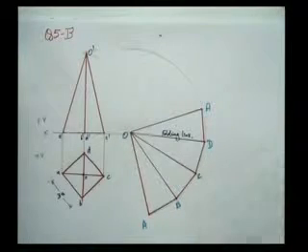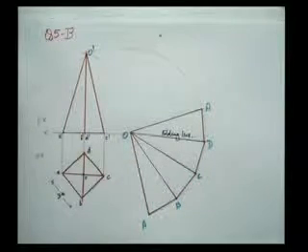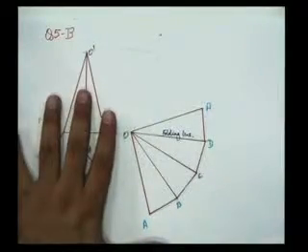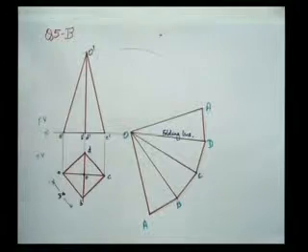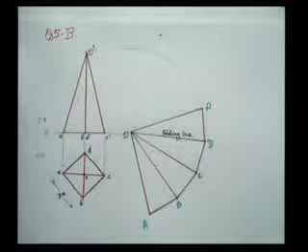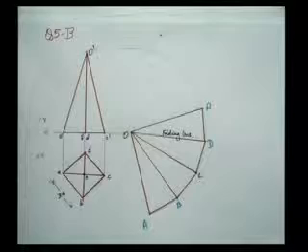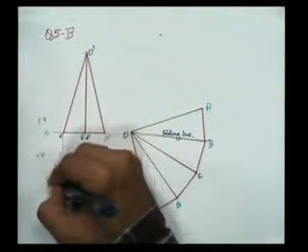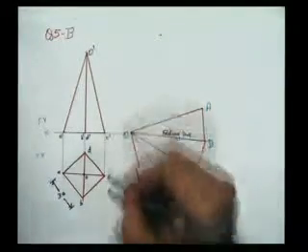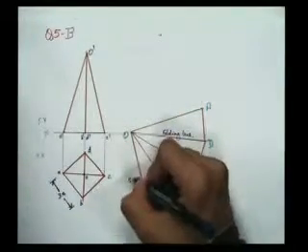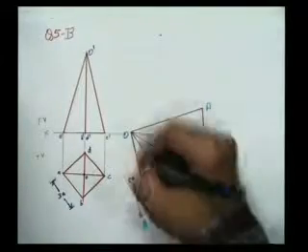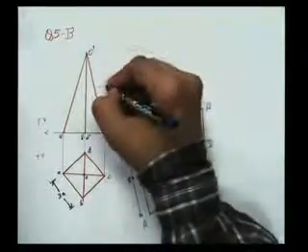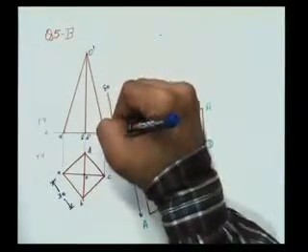That is why this is known as development of surfaces: this is a solid surface that is given to us, and this is the two-dimensional plane with which this surface can be created. So this is the solution of the problem 5b. Now please don't forget that marking the dimensions and labeling them are very, very critical. So I will do that. This is 80. You should use a good ruler and scale to mark the dimensions. Again, this is 80.